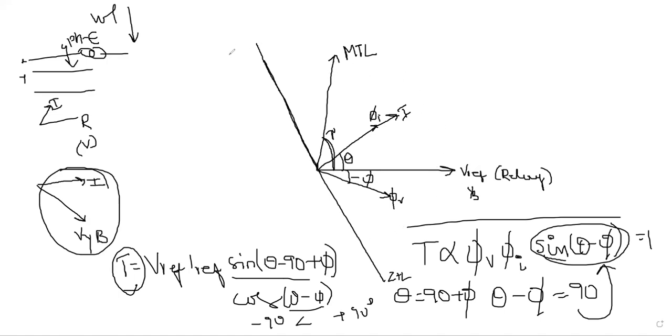This is the forward region. Again, for the directional relay there would be some leakage current, so I have to give some threshold value for this. If I give a threshold value of current like this, then this is the restraint position. So the relay will operate only in this zone. This is the forward zone.